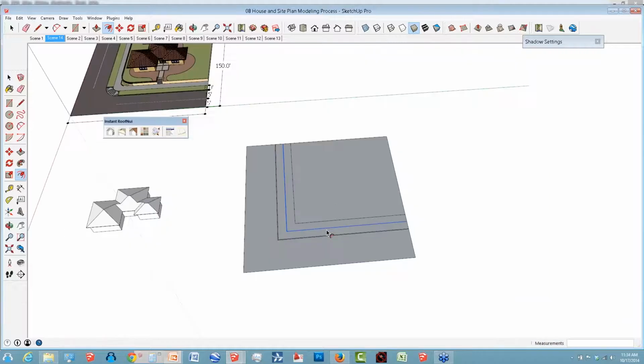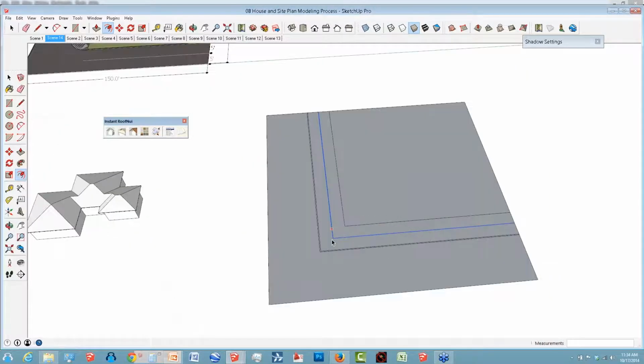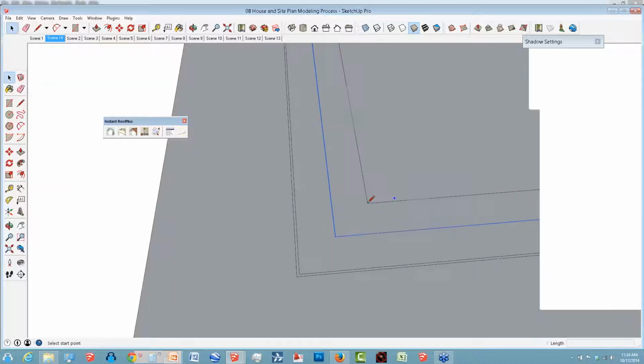Next, I'm going to draw some drafting lines here, some lines for me to reference going out. Here's the important thing about working with SketchUp that's worth mentioning right now. Whether you're drafting this in SketchUp or importing in your CAD drawing, you're essentially going from 2D to 3D. You're using your 2D to reference because that's the best way to conceive of something. When something's in 2D, you add these surfaces, you extrude them, then you can have fun figuring out how to create the rest of the extrusions that represent your site. But in this case, what I'm doing is just drafting all this out.